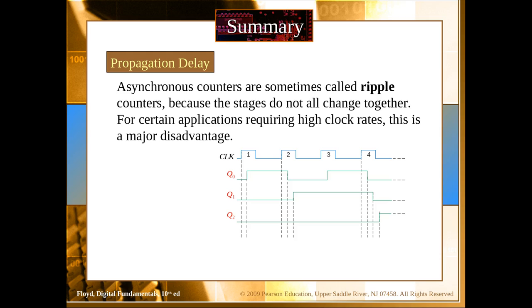We have seen in the previous lecture that there is a certain amount of delay, probably in nanoseconds or milliseconds, between the clock input and the time when the output can be achieved. But since each subsequent flip-flop is driven by the output of the previous flip-flop, this delay is added. So for example, the first flip-flop, if it has a certain delay, as you can see in this waveform, the second flip-flop would have 2 times the delay because it is added upon the delay of the first flip-flop.